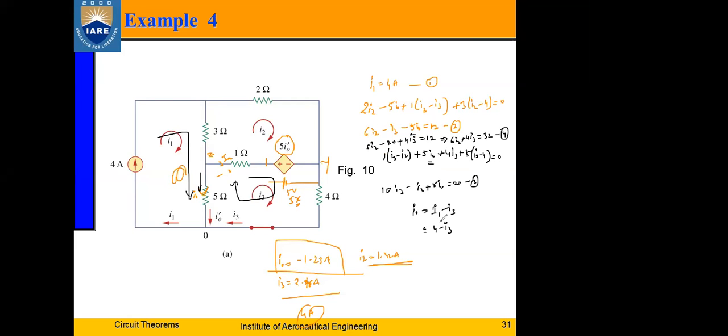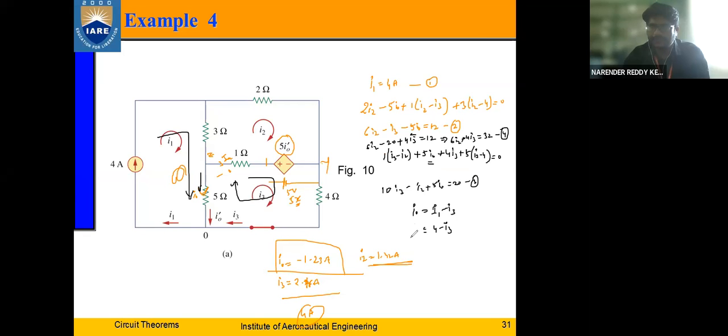Okay. Similarly, we substitute the same thing in equation 3, where the values change. So I can write it as minus I2 plus 5 4s is 20, and minus 5I3 with minus 10, so I have plus 5I3, which is equal to 20 now. If I send this 20 there, it will become 0. So I get the equation minus I2 plus 5I3 is equal to 0, equation number 5. Is that fine?